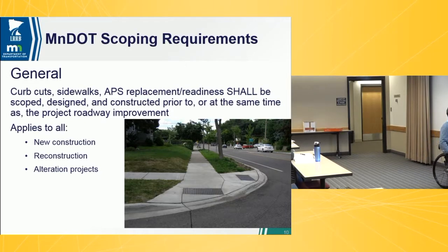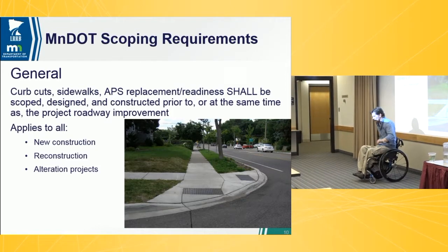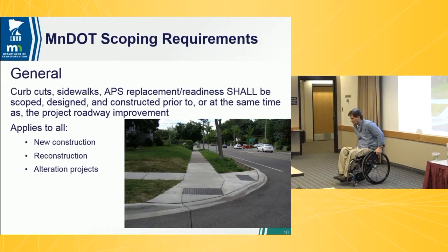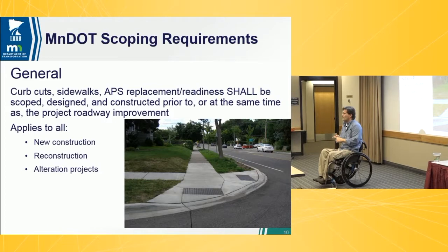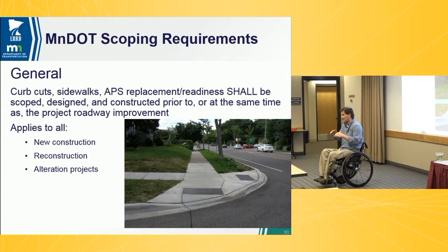And again, here's what our sidewalk fixes may look like. It's partial fixes, and because we have thresholds, we're leaving some, removing some other areas, taking another patch, whatever it is. So our thresholds are based on condition. So poor or failing sidewalks, that's where those trip hazards are, those busted panels, things like that, faulted joints. So that would be one trigger.